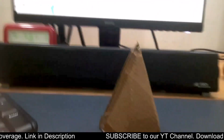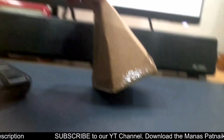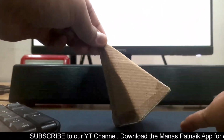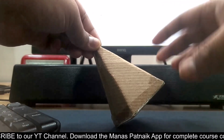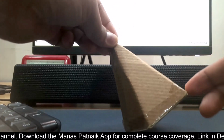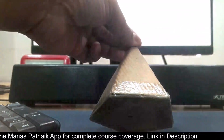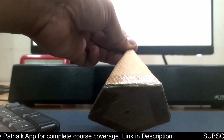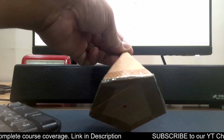So what have we done so far? Sir, basically we started with this as step number 1. This was our step number 2. In step number 2 we gave this edge 45 mm height above HP. In step number 3 we will rotate it until this edge becomes parallel to the vertical plane. Now you can see this edge will become parallel to this vertical plane. Vertical plane is behind, right? Okay, so this is what needs to be done. This is going to be our step number 3, right?